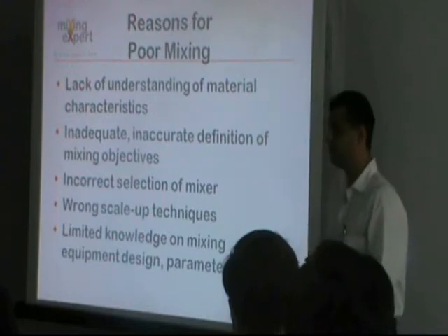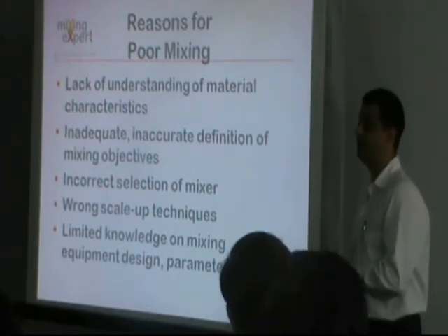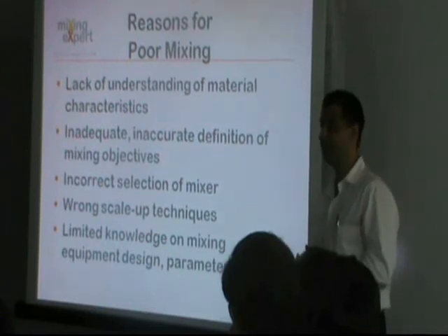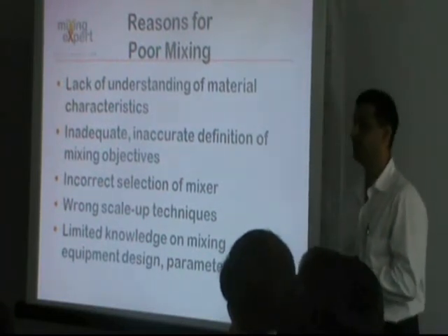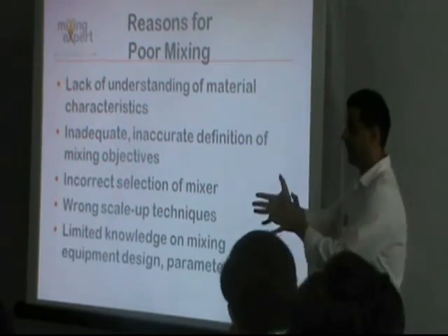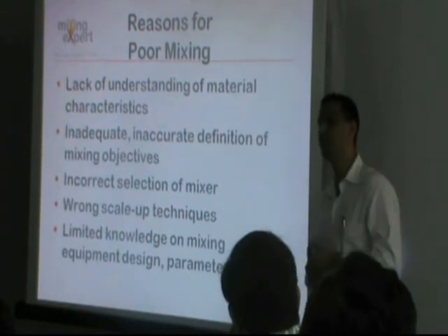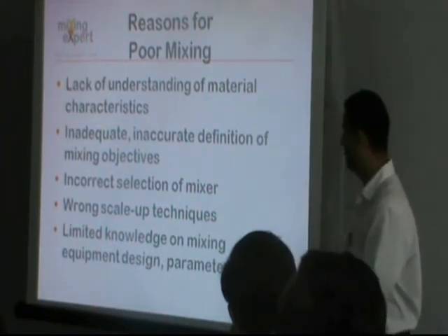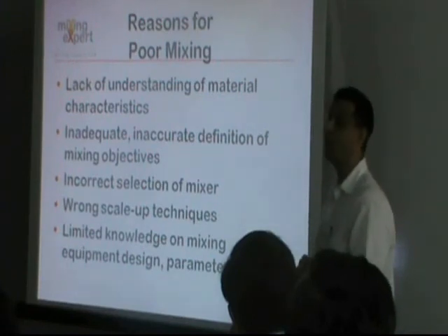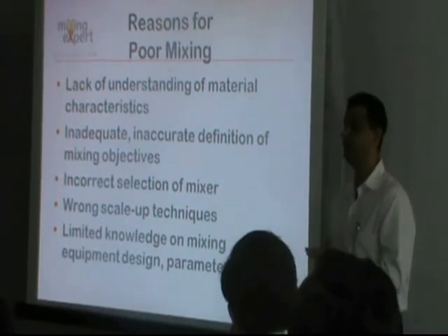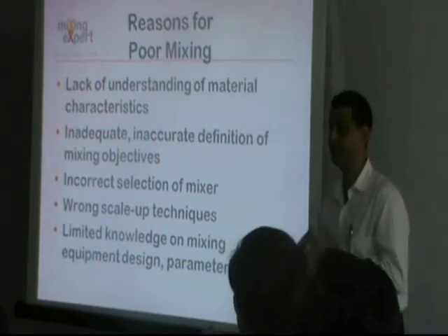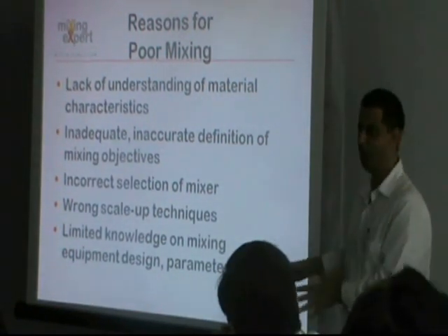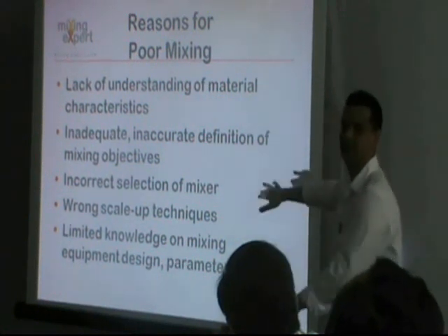Wrong scale-up techniques. When it comes to applications where you don't have much of a background, much of anything which has been studied, it could again be a challenge to develop a production size mixer. So you would have to conduct laboratory trials, take the results from a laboratory trial, and bring it to scale up. I will share with you as we move forward an example of how expensive an incorrect scale up can be. And definitely we all need to update ourselves on knowledge of mixing equipment design. What would be the capabilities of a particular kind of mixer, what would be the parameters in mixer selection. It is nothing complex. It is all within this, and so long as we take care of this, we should not have any challenge.